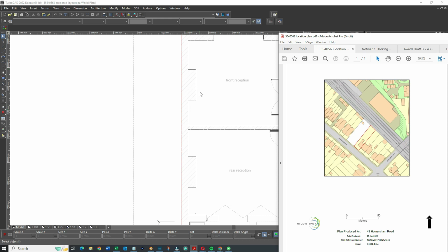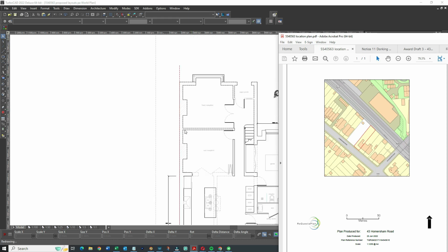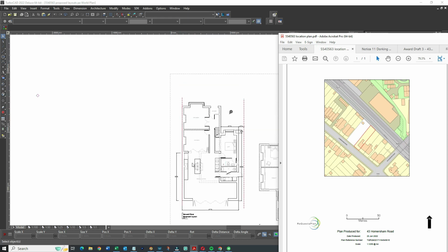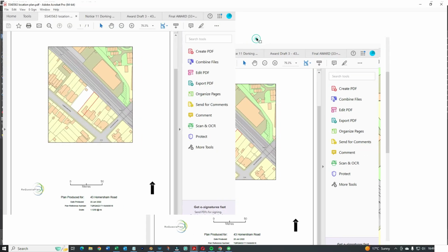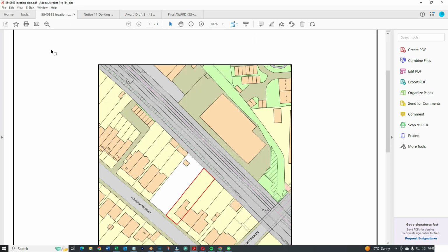Taking out this chimney breast, party wall agreement. Excavating, digging for this extension, party wall agreement. So that's how it works. After you work out that you need it, you have to find out who owns next door, who the freeholders are, and that's done through the Land Registry.